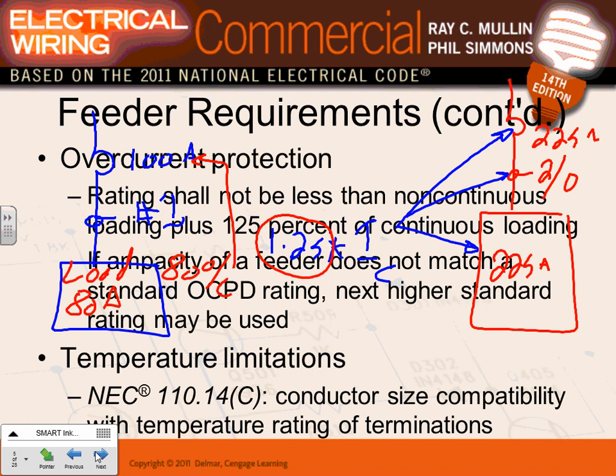Unless it's 100% rated, which is after 1,000 amp or higher, it's slightly different. 1,000 amp switchgear, can I get 1,000 amp out of 1,000 amp switchgear? Yes. Why? Because then they make the circuit breakers bigger, more robust, and they can handle the continuous load for 1,000 amp. Does that make sense?